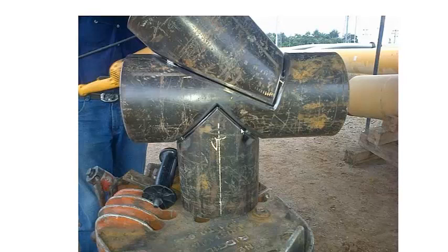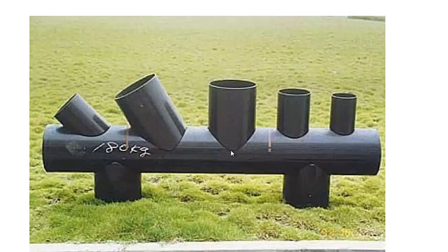There are some modifications as pipe gets bigger diameter that will actually round off this point and line up the inside diameters. And so when you see some big pipe that are branch, like a branch test, round intersections, this will be rounded off. So kind of like here in this that I'm showing you here, maybe this one's the same diameter as that one, and they've kind of rounded this off to line the IDs up a little more than the ODs.